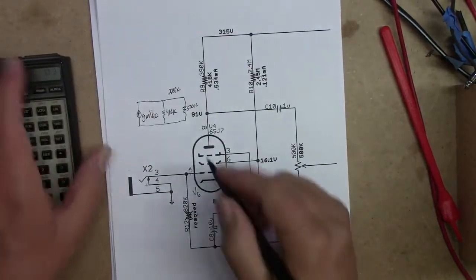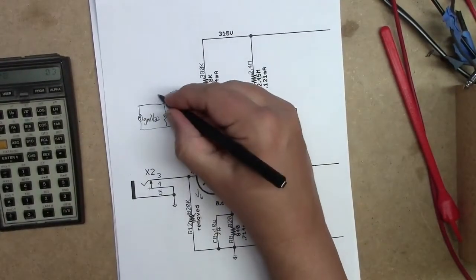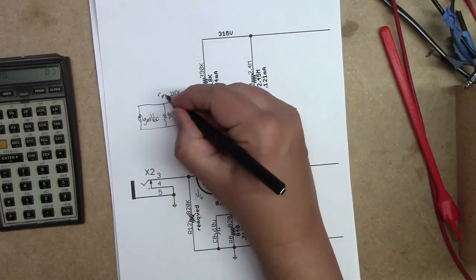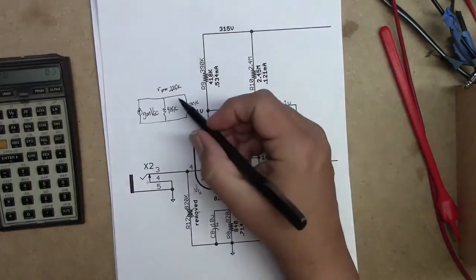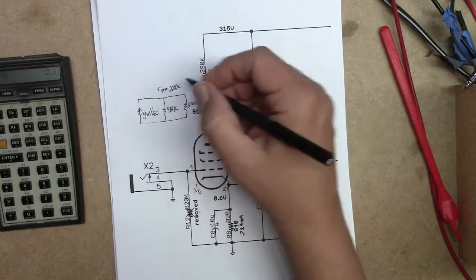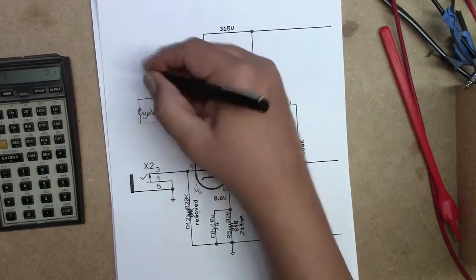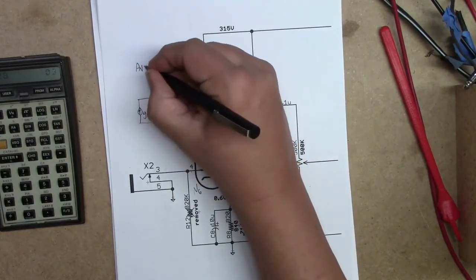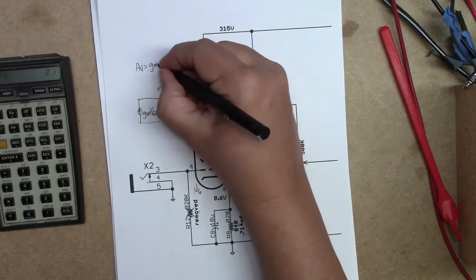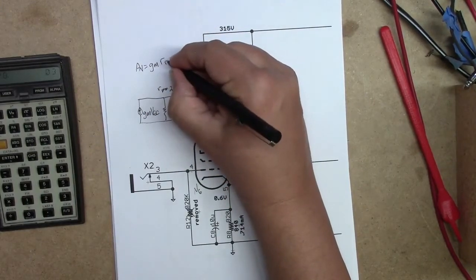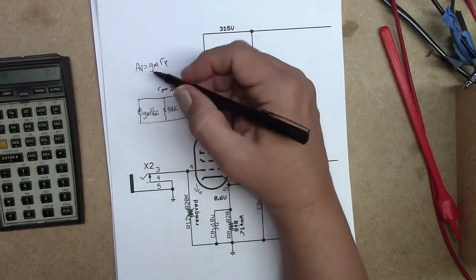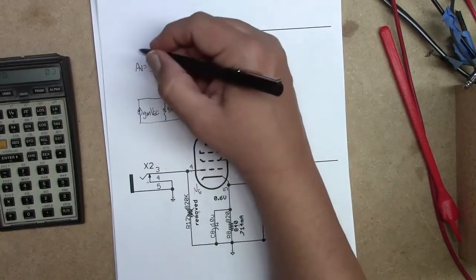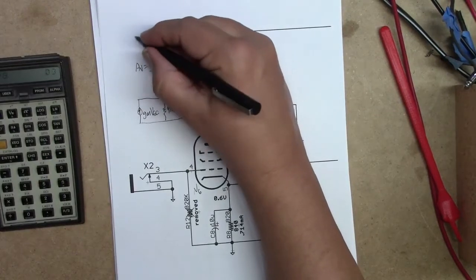This is little r sub p, which is the AC equivalent for the plate, the impedance that the plate sees. So in a pentode, the voltage gain is equal to G sub m times little r sub p, and our voltage gain at the midpoint, which was 1K, we had